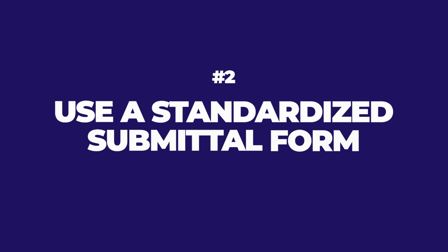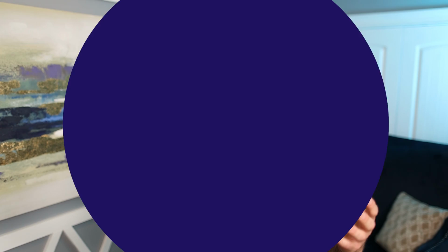Number two, use a standardized submittal form. Utilize a standard template so that the recipient, the design team, and the trade partners for that matter can get used to the consistency, and include typical items like project name, number, date, and any other pertinent information.